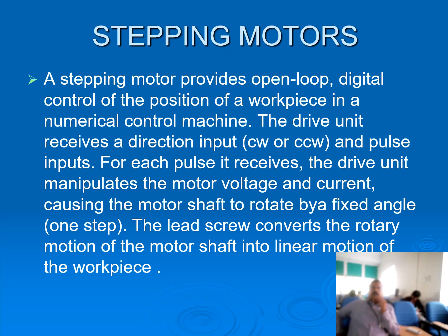For each pulse it receives, the drive unit manipulates the motor voltage and current, causing the motor shaft to rotate by a fixed angle, one step. The lead screw converts the rotary motion of the motor shaft into linear motion of the workpiece. So here the rotary motion is converted to linear motion by the lead screw.